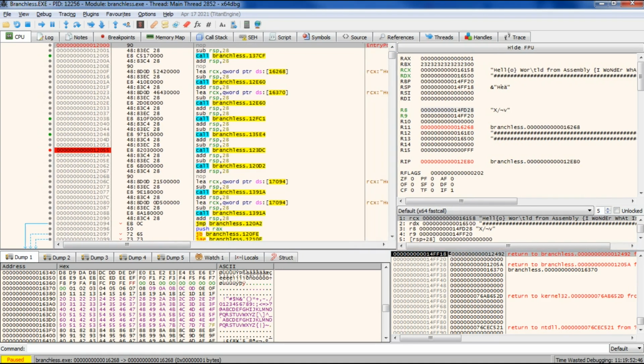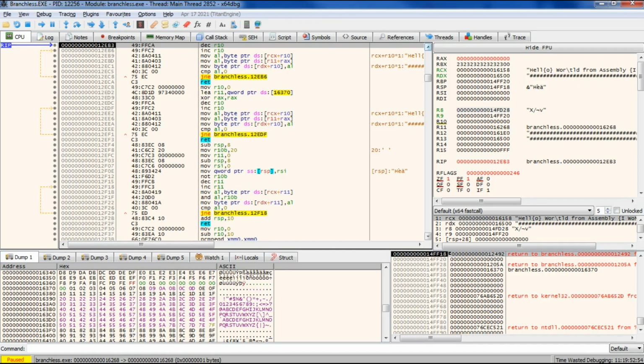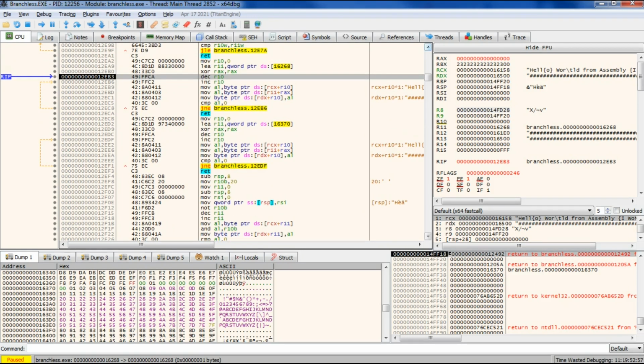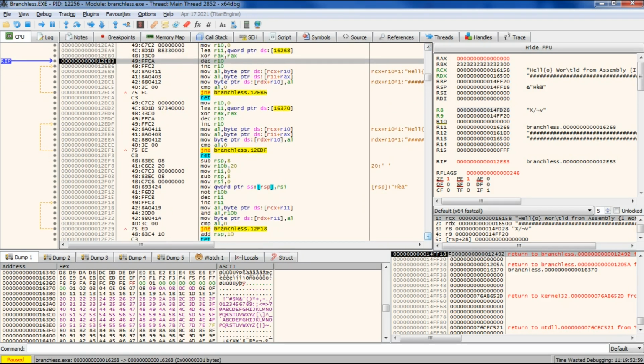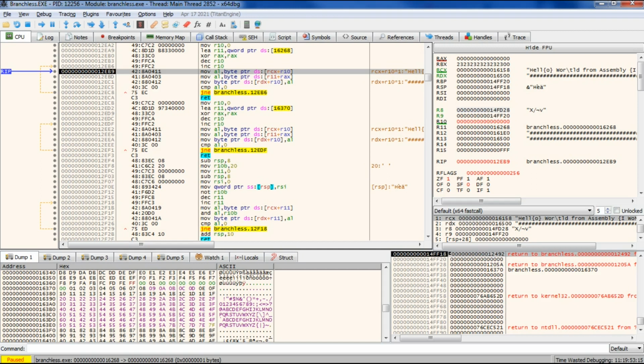So let's find out where we were again. There we go. Hit F8, it'll take you there. And let's set our screen back. Okay, so R11 is the address of our lookup data. So we're going to decrement, subtract 1 from R10, fills up with F's. There's our start of our loop. Add 1 back to R10. Now we're at 0 again.